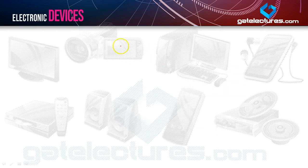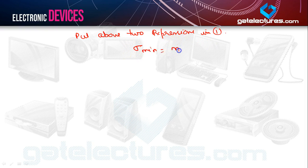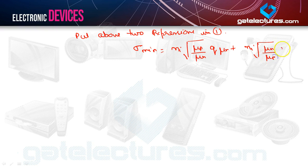Put the above two expressions in 1. We get sigma minimum as ni square root of mu p by mu n times q mu n plus ni square root of mu n by mu p times q mu p. So sigma minimum comes out to be 2 ni q square root of mu n mu p.